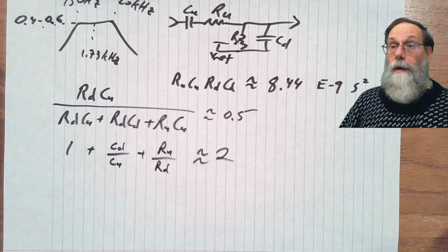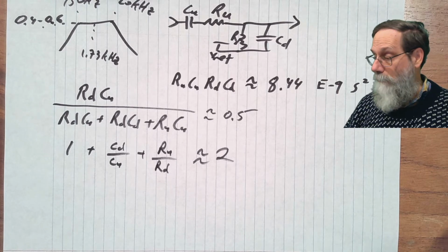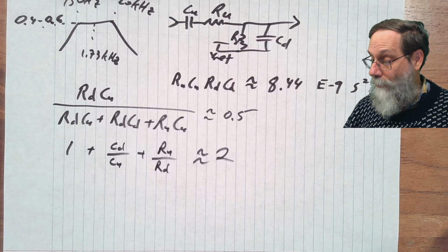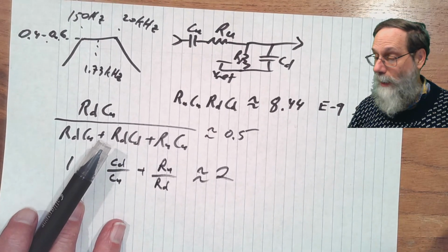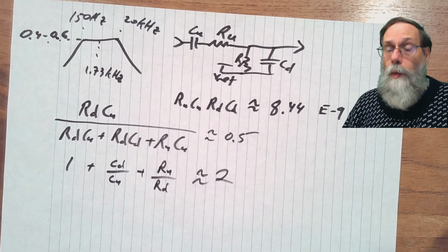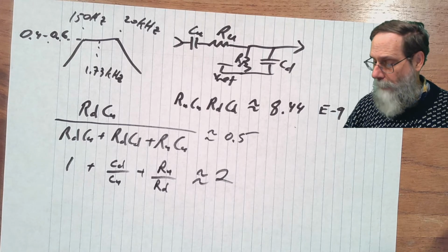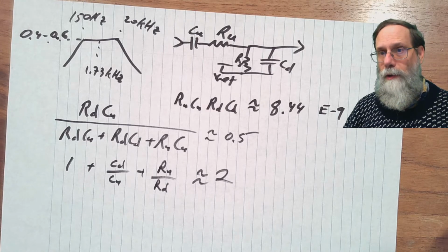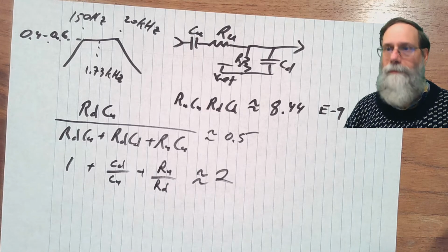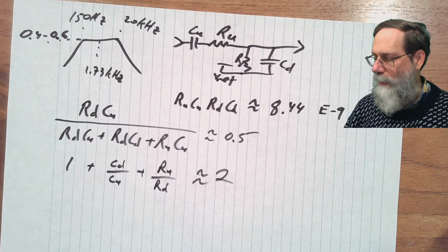Alright, so this is, like many engineering problems, somewhat under-constrained. We have only 3 total constraints on our design here, what the two corner frequencies are and what the overall gain is, but we have 4 parameters. So at least one of the parameters we can adjust freely, just scaling everything. It's generally harder to get good capacitance values than to get good resistance values. They're more widely spaced in the components that are available usually.